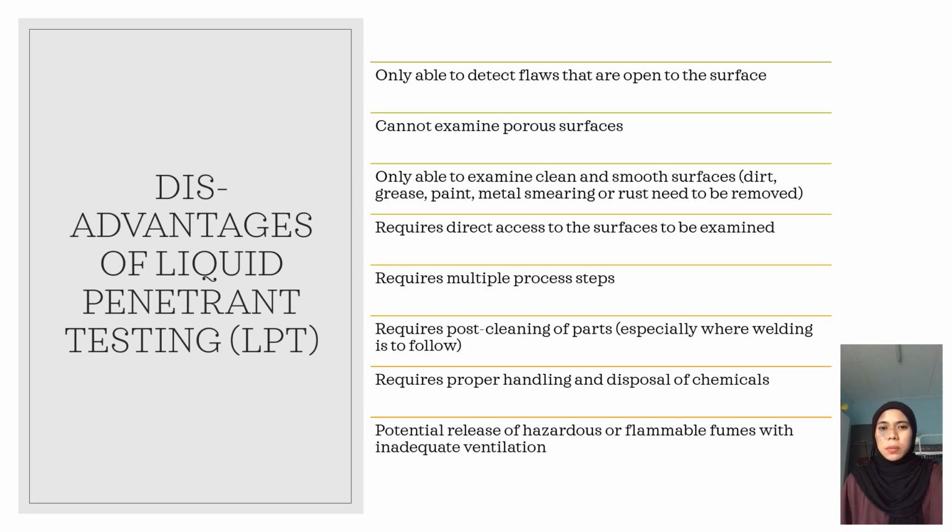A disadvantage of liquid penetrant testing is that it is only able to detect flaws that are open to the surface. It cannot examine porous surfaces and is only able to examine clean and smooth surfaces.